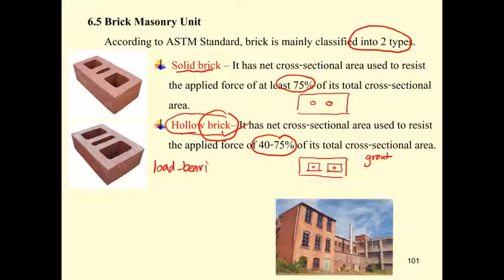In the Western world, the form of structure uses what is so-called the load-bearing wall to take care of the vertical force. So they don't have columns or beams, such as the ones in Thailand. Our culture comes from building the house from timber, so we need to have the beam to support the floor and transfer the force to the column. But for the Western culture, the buildings are built by brick, so the load transfers from the floor directly to the wall, such as this kind of building.